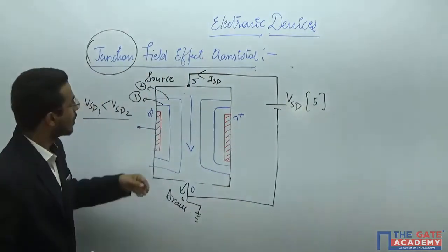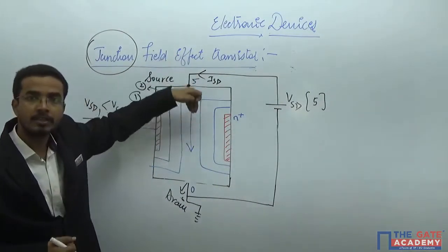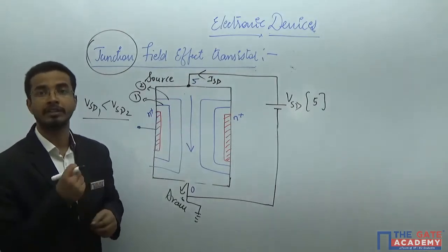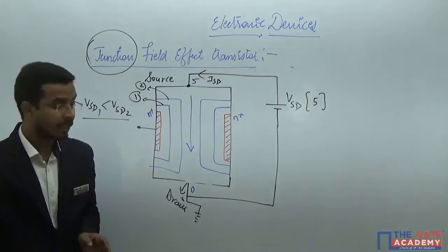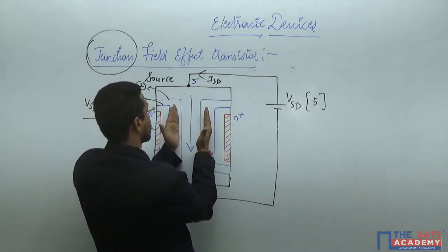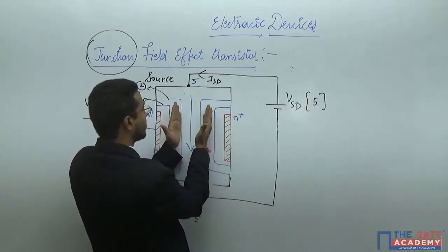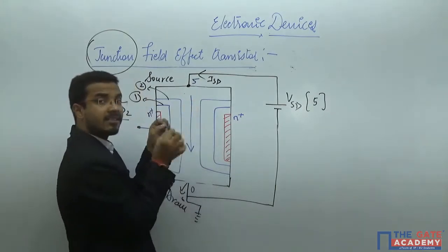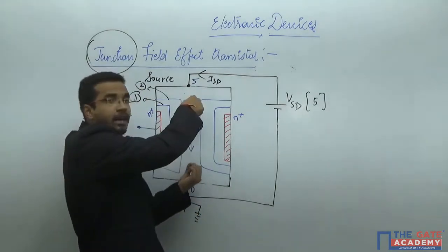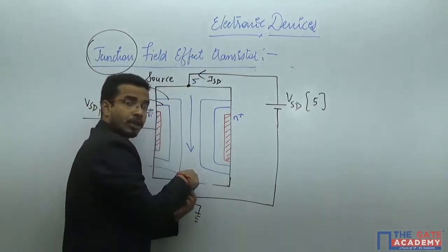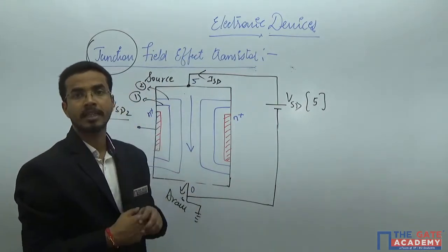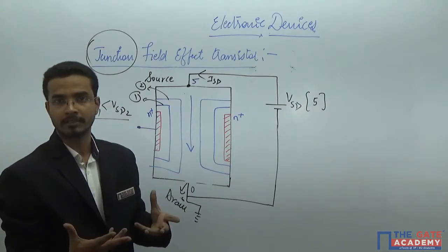You are also increasing the electric field, that is why the current will also increase up to some extent, up to which these two junctions, whatever depletion regions you are making, are not touching each other. As they touch, the available area for conduction of holes from the upper body to the lower body becomes zero, and at that time you will get zero current from the device.